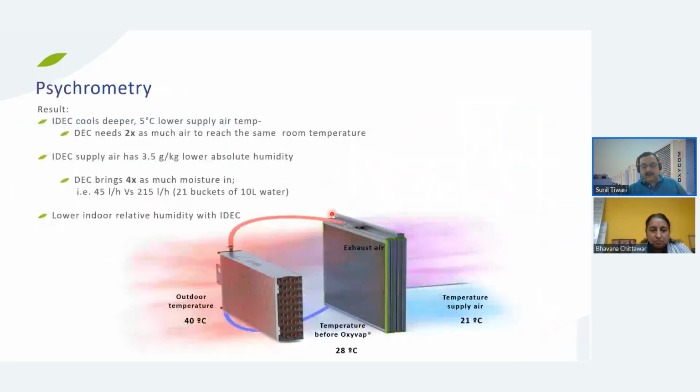Now, how does it help in the application? Assume we have an area that we need to cool, and we know the heat load of that area. In the design of evaporative cooling, you have to ignore latent heat, because in any case the latent heat of the building is thrown out. It's like pushing it out, scrapping it out of the building. So it's not to be counted. Only sensible heat is what matters.